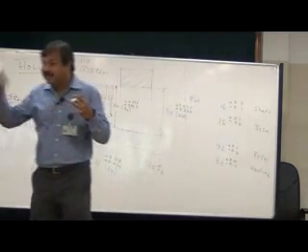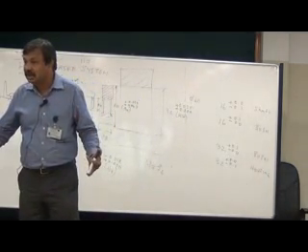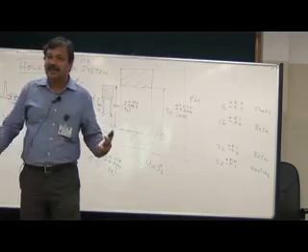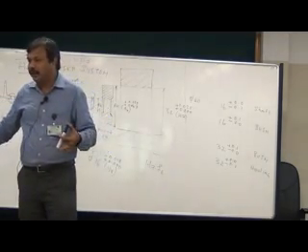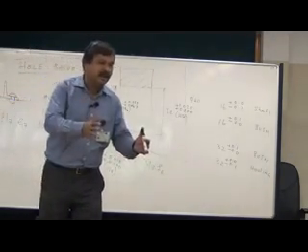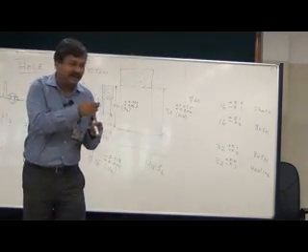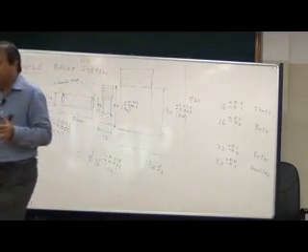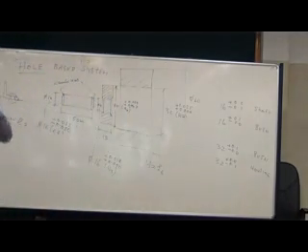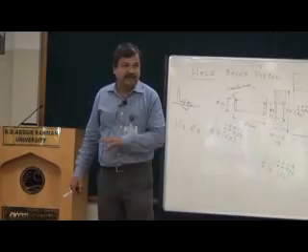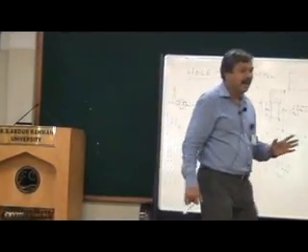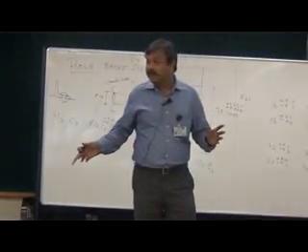The temperature distribution within the furnace is not uniform. Temperature is not the same at every point. You know that ceramic formation takes place at a particular temperature, but inside the furnace, the temperature distribution is not uniform. If the temperature is low, you have underburning taking place. If the temperature is high, you have overburning taking place.